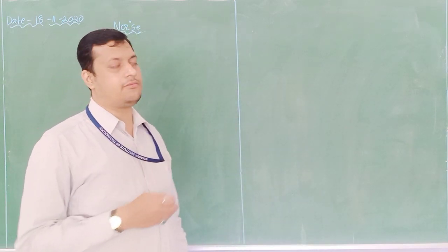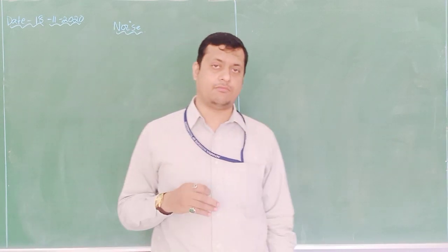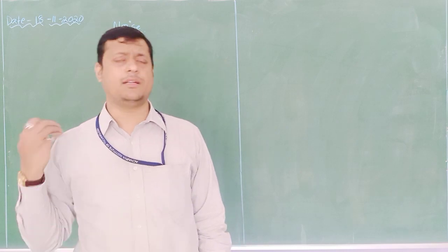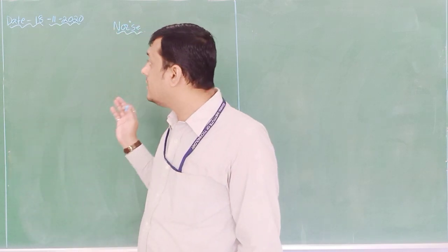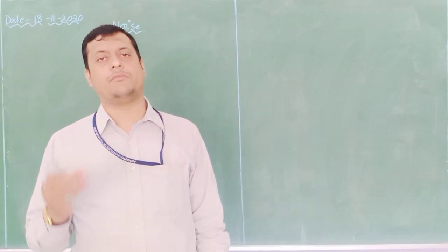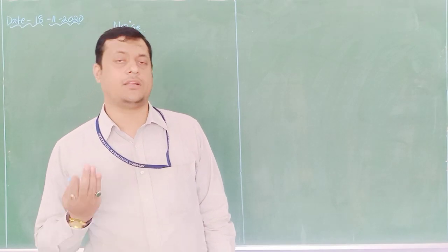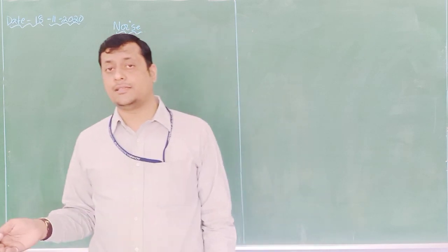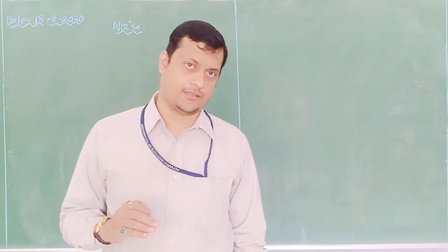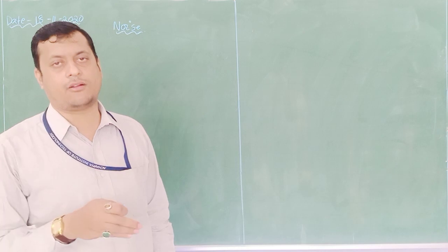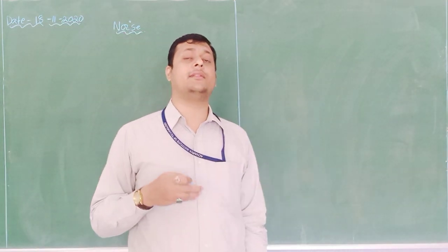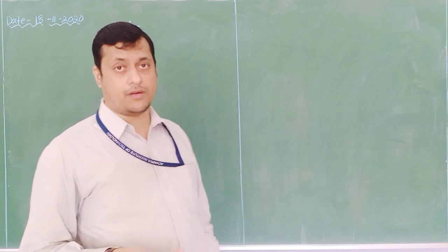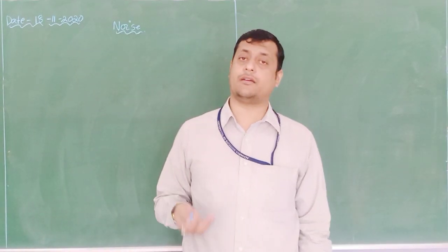Last class we discussed the DSB-SC system as well as the AM system. Now we will discuss the SSB-SC system, with the detection method we are using being synchronous detection. Later on we will discuss envelope detection, and with the help of the envelope detector also, how you can identify the signal to noise ratio at the input side, the signal to noise ratio at the output of the demodulator, and what the figure of merit is.